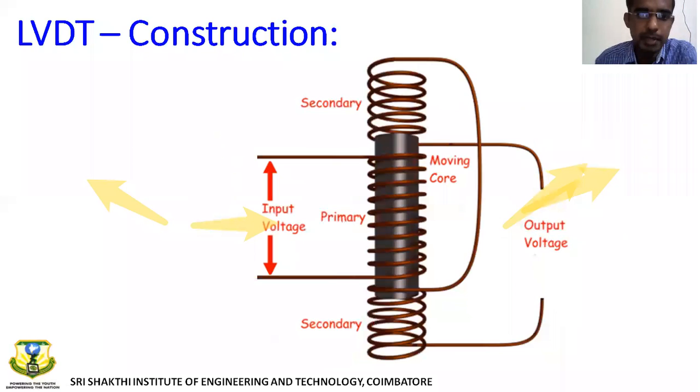If you look at this, you will understand easily. So this is an animated, not an animated one. See the core, the iron core is movable. So wherever next to it or a GIF animation, that will tell you how it works. The core can be moved upwards or downwards according to the movable arm. So when the movable arm moves, see this is the primary. See my arrow marks, here the wind comes and goes here. So this is primary. This is secondary 1. The end of this goes to secondary 2, look. So secondary 1 and 2 have output voltage, right?